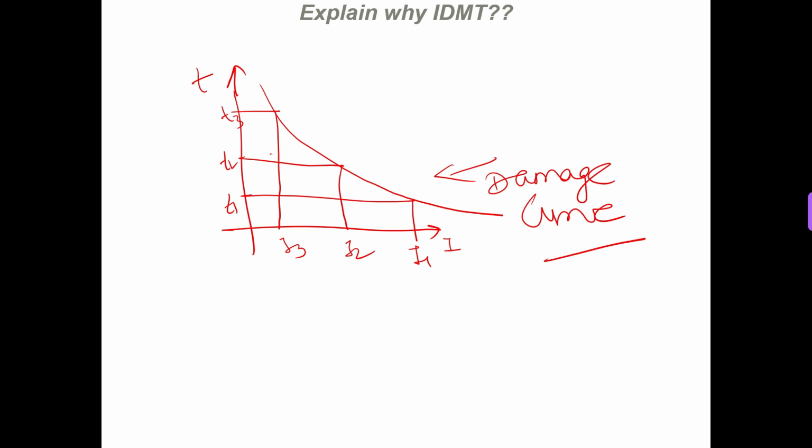Now if we want to use a protective relay to protect this type of equipment, our protective relay should exactly match this damage curve. So we should have a relay which exactly matches this damage curve. Whether it is an electromechanical, digital or numerical relay, it should have a characteristic which matches the damage curve of this equipment, and it should keep a certain minimum distance at each point. That distance is called coordination time, which we will discuss in our upcoming slides.